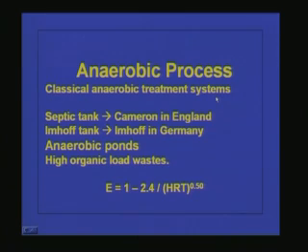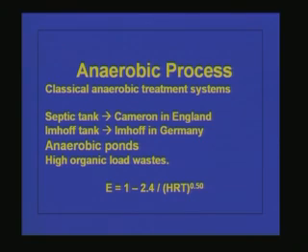So in anaerobic lagoons, we can go for high organic loading, and the waste will be staying there for a long time. So what will happen? Because of the high organic loading rate, whatever air or oxygen is entering from the atmosphere will not be enough for maintaining an aerobic condition in the system. So the entire pond will be in anaerobic condition. Because of the anaerobic bacteria, degradation will be taking place, and a portion of the COD will be getting removed from the system.